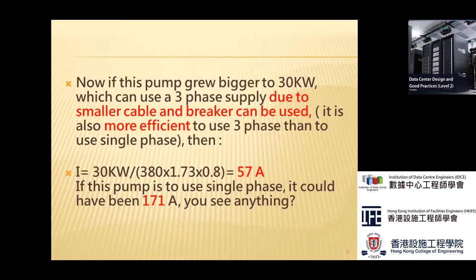Not the voltage, but in terms of being more powerful to turn a rotating machine, right? Either motor, rotor, chiller plant, fans, pumps. We have to use a three-phase supply. And in actual cases, anything more than say 3 kilowatts, you can use a three-phase supply already if you want it.